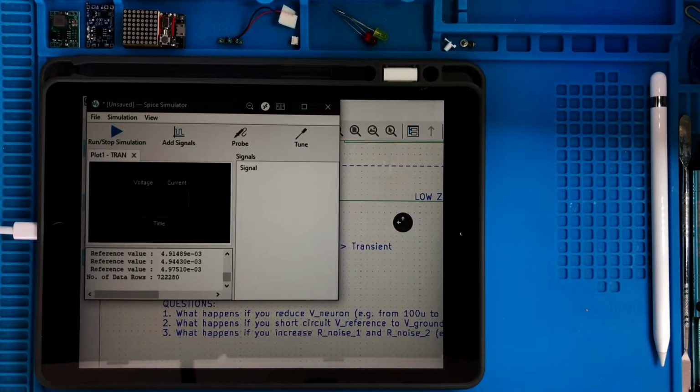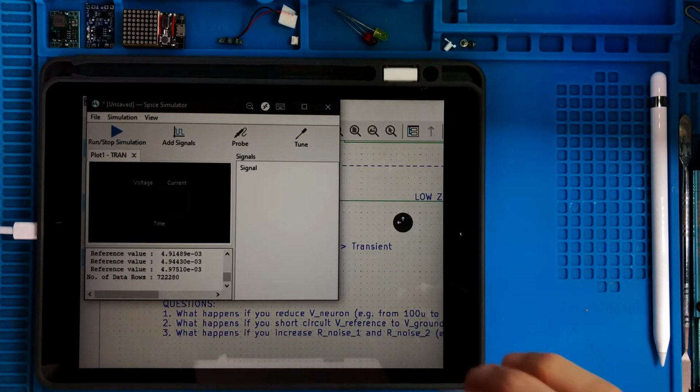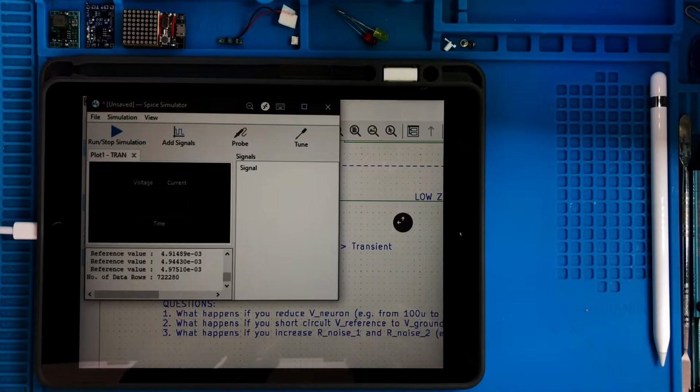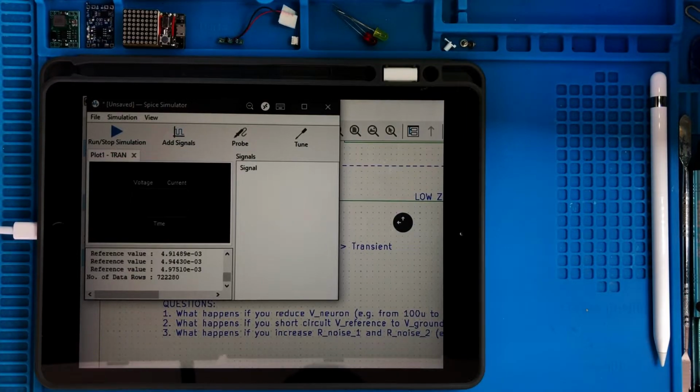It takes into account the netlist representing the spice model of the component. If you remember in the datasheet, all those transistors and resistances internally implemented in the microchips. Then it took into account all the external components we attached, all the source voltages, and in a few seconds it did something that we probably can never do in our life because it's too much computation. But in principle it did the same thing.